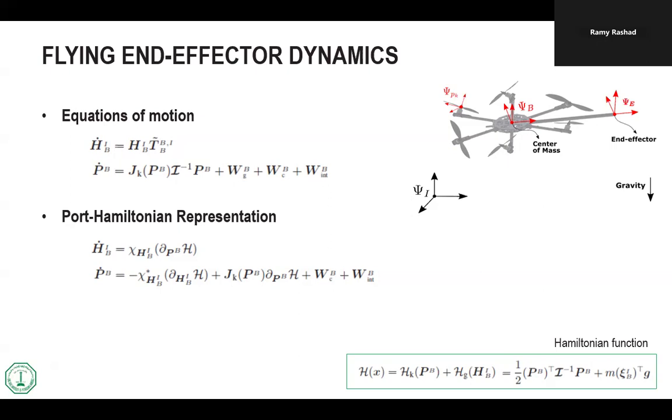So it's easy to immediately see that the gradient of kinetic energy with respect to momentum is equal to, in the previous example, what was it? It was velocity. So here, the gradient of the total kinetic energy with respect to the generalized momentum, what would it be? The twist, which is the generalized velocity. This is not a coincidence. It's always the case.